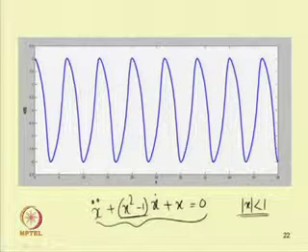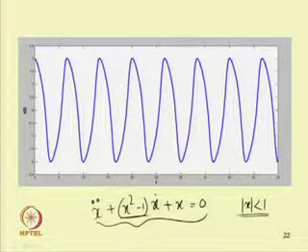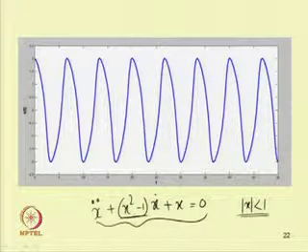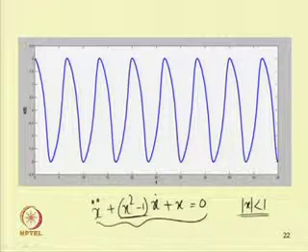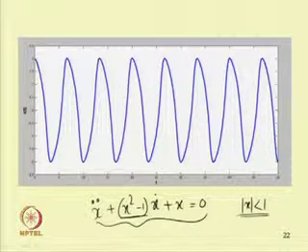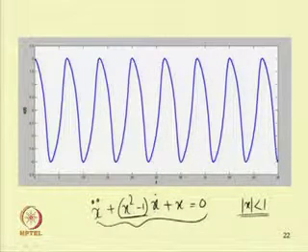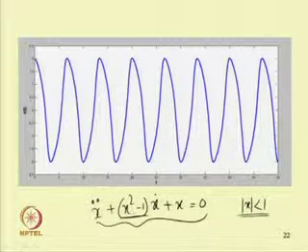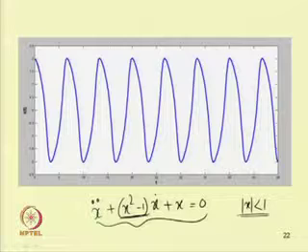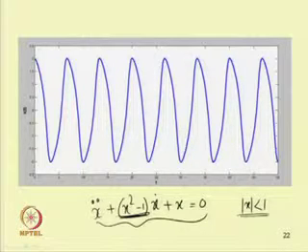When it is negative, the system will have a tendency to become unstable, or the response will grow, and when it is positive, the response will tend to decay. That is why one can have swelling, or an increase in response, when this whole term is negative, and at that time it will expand.